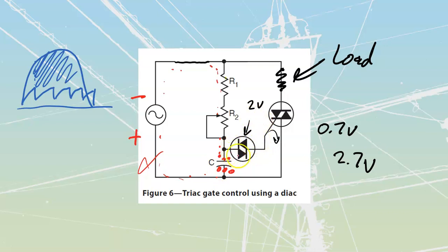Once again, we need 2 volts and 0.7 of a volt for this one over here to turn this on. So as we're building now in this negative direction, here's my negative sine wave. We are also going to have a negative sawtooth that's going to start to build like that. Whenever my first sawtooth hits its peak enough to turn this on, we will then be able to drive the electrons. See, they're going through in the opposite direction now.